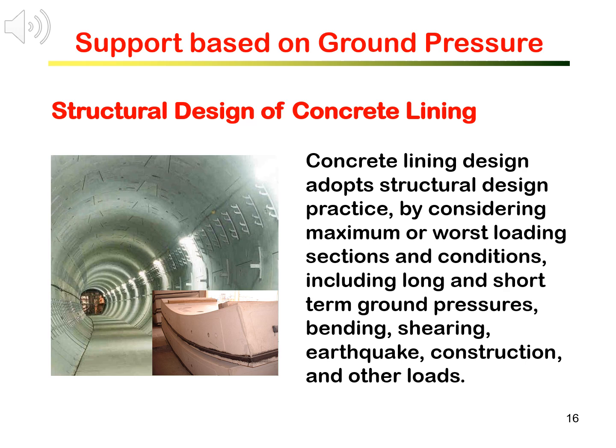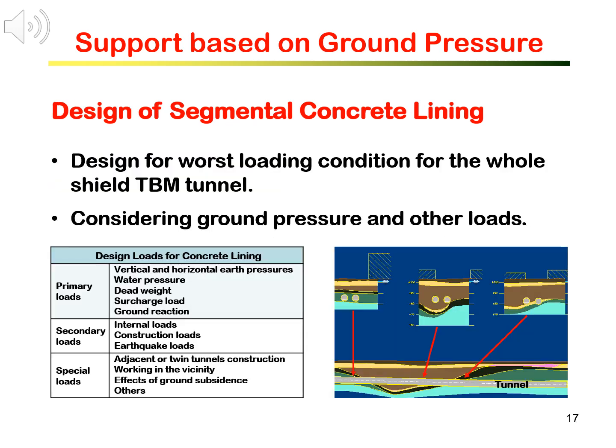The photos here show a typical tunnel supported by segmental concrete lining and the concrete segment. Segmental concrete lining today is a more or less universal tunnel support method for tunnels excavated by shield TBM in poor and weak rocks and in soils. Design of concrete segments follows concrete structure design practice to meet the designed load.